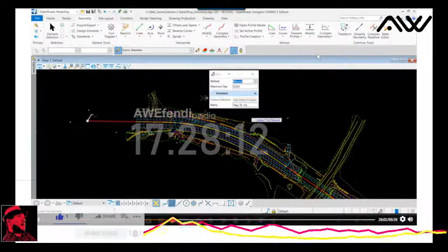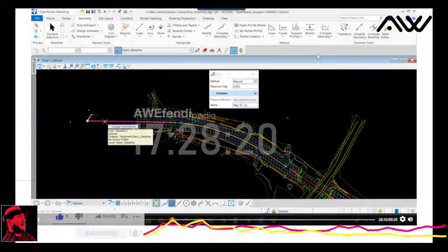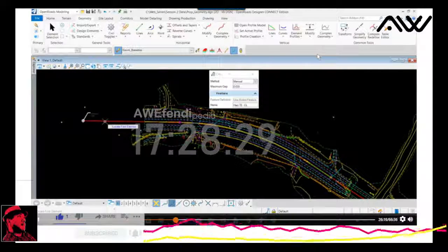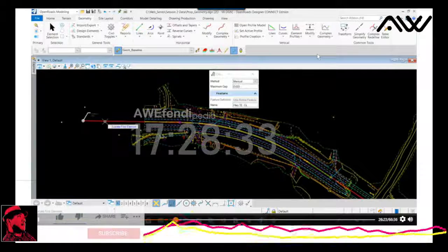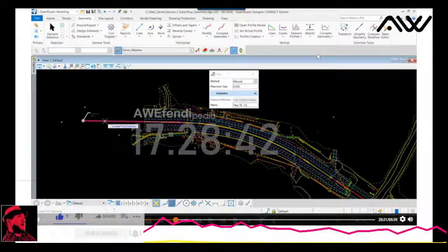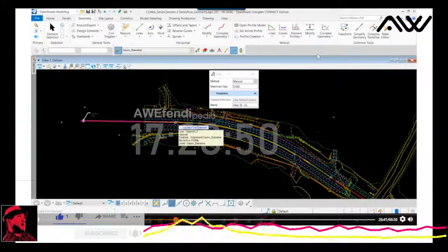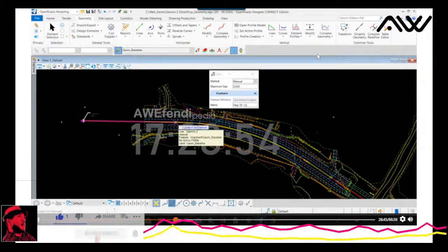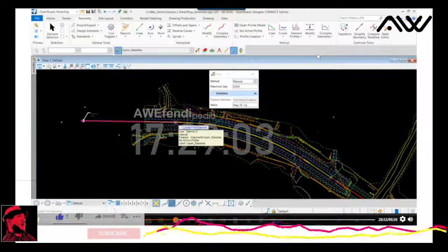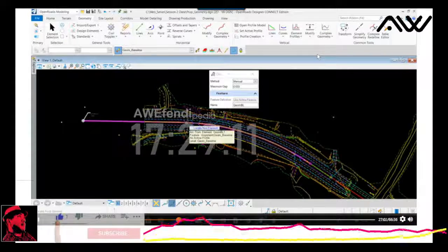And now, I'm going to do this manually in order to just show you something. You'll notice as I move onto the element to begin picking the first element, what I want you to note is that purple arrow on the east end of the element. That purple arrow indicates the direction in which it's going to join elements. Okay, that's the direction of the element that it's going to create or that it's going to join. Okay, meaning stationing is going to go in the direction of the arrow. Now, notice where my cursor is. If I move and I select that element on the opposite side, notice what happens to the arrow. So where you select the element has a direct impact on the direction of the element. Okay, and I'm showing you that just so that you'll avoid potentially picking the element in the wrong end and then putting them in the wrong direction. Okay, so we're going to pick it from the opposite side, the western end. So we're moving in the eastern direction. I'll select it, and then I'm going to go through selecting each element in the same direction just to be sure I'm sequential.